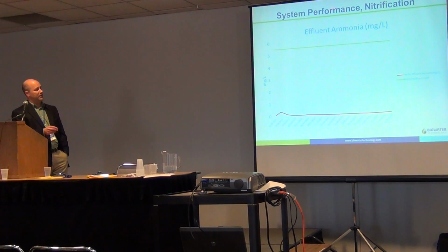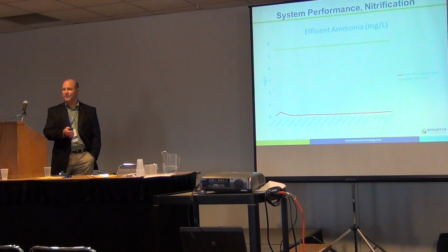And to elaborate on that, here's your effluent ammonia limit, and this is the summer limit of 5.5. And there's the effluent ammonia, even coming down to very cold temperatures in January, still well below their discharge limit. So varying flow, varying loads, varying temperatures, and at the end of the day, a very robust treatment system. Any questions?